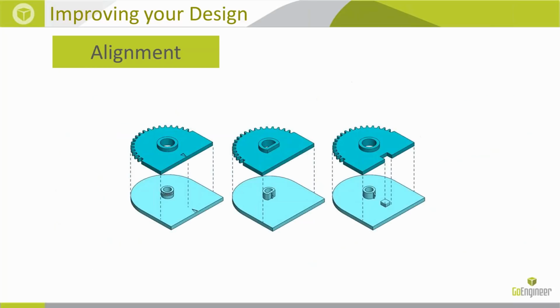So this one I really like. This is 3 examples of assembly and alignment. So in the first one, you have a screw-on or a twist-on assembly, but they molded an arrow indicator. So that gives your end user some feedback on what the final position should be. The middle one gives your user auditory feedback when you snap something in place. And once you get past that stepped edge, then they understand that this item is locked in place.